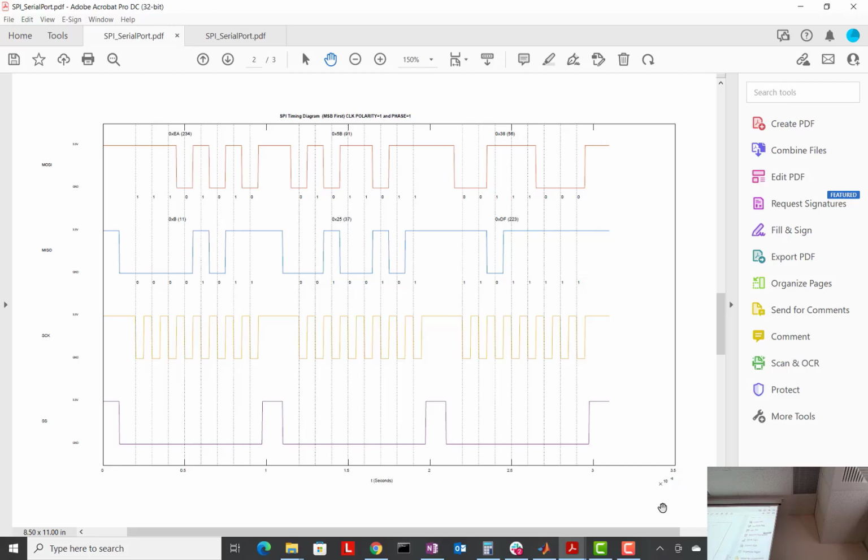Okay. I know, I don't like it. It's always a pain in the rear. And what's also a problem a lot of times is the data sheet isn't super clear which mode it is. TI has one data sheet that I dug through, and according to the data sheet, it says it could be both mode 0 and mode 3 or something like that. I've never been able to get this chip to work in mode 0. It only works in mode 3 for me. And that causes little headaches. You have to figure out if your code's working right and all that.